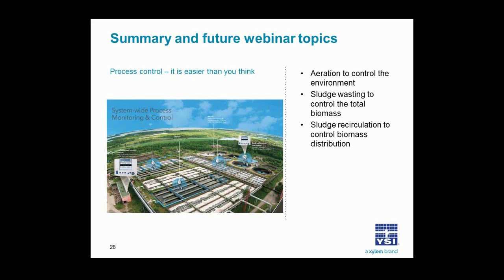And so the question is, in general, yes, but you also have to consider that your sludge blankets may be increasing because your SRT is too high. So a response to the rising sludge blanket may also include increasing the wasting rate. And so, for example, I mentioned that centrifuge spin control test. One of the neat things about that, although it's a batch test and we don't sell centrifuges, if that's what you've got, it can give you the information you need so you know whether you need RAS control or waste control. But thanks for the question.